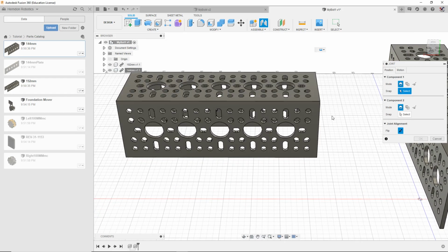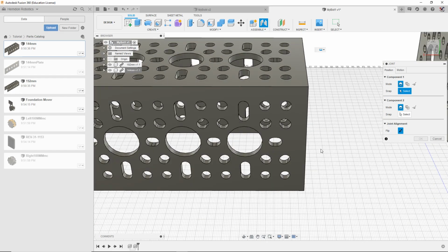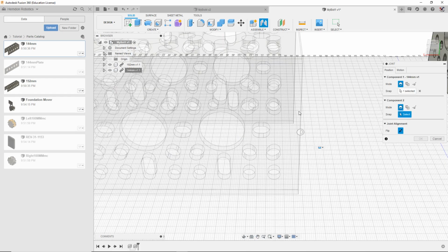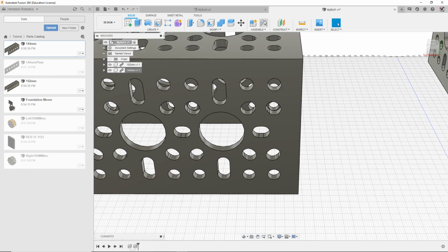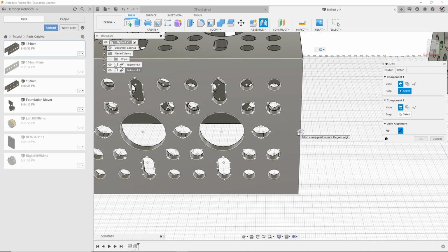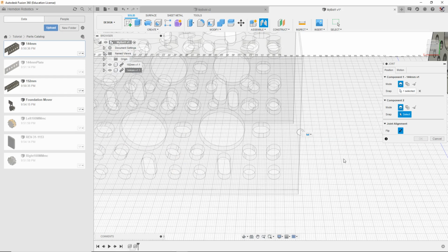So on the 144mm channel, we're going to come here, and you see this little plate. We want to kind of put this flat, because it can go at all angles. And you want to select this line. Let me go over this once again. We have this line, and you can select different points. We want to do automatically in the middle, which Fusion knows. And then we kind of want to put it to the side, so we're flat on this way.